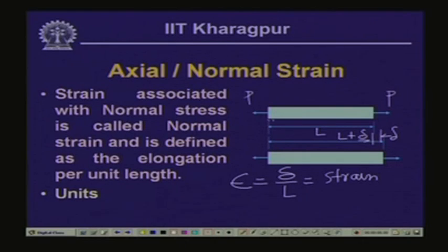The load, the force which is acting in the body, is in the axial direction, and we assume that the deformation is uniform at any point along the length of the body, and thereby everywhere the strain is the same.